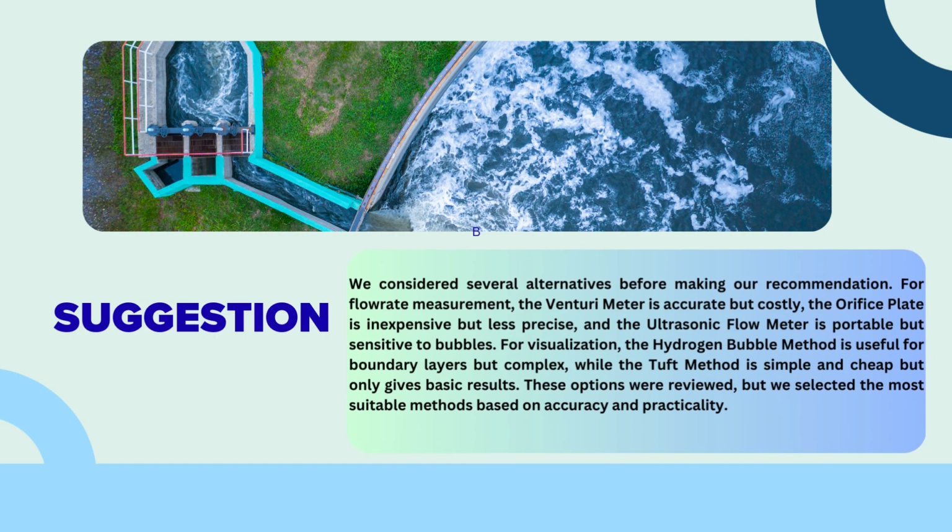Hi, I'm Muhammad Kamisan bin Zaini. I will present about suggestion and recommendation. Before finalizing our recommendation, we carefully reviewed several alternative techniques for both flow rate measurement and flow visualization. For flow rate, the Venturi meter was considered for its high accuracy, but its cost and installation complexity made it less practical. The orifice plate offered a low-cost solution, though it came with reduced precision and significant pressure loss.